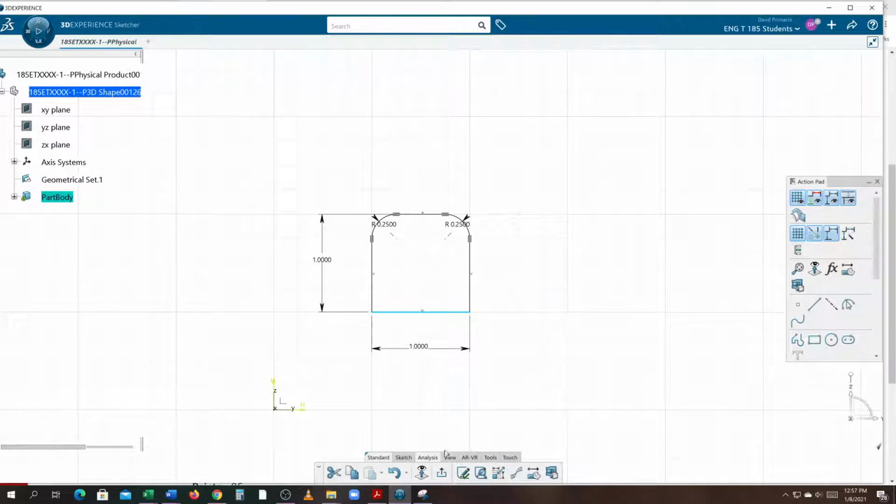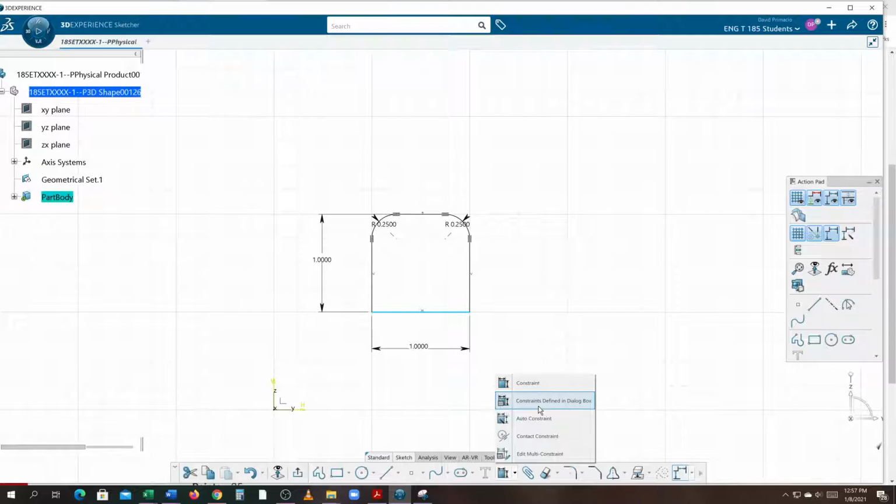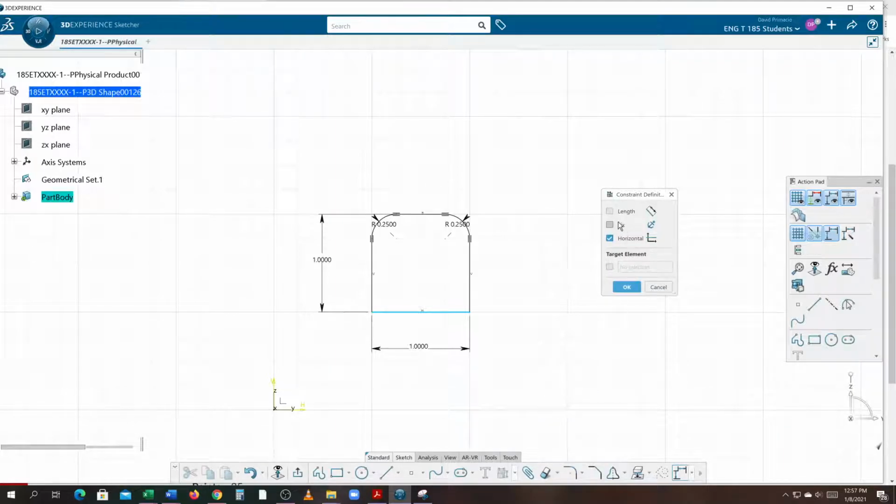When you grab that line, under the Sketch tab at the bottom, where you see constraints, there's an arrow to the right of the constraints. You hit define constraints, the define dialog, and we hit fix, and it establishes an anchor. And this top line becomes green, saying this is my anchored line.